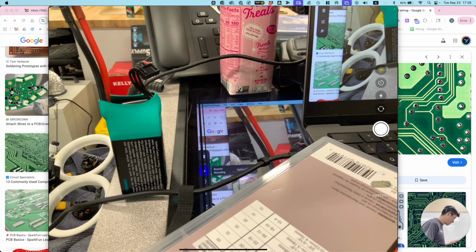Go ahead and place that split behind, and then slip the heat shrink on top. There you go. And then keep putting the heat shrink until it covers, and then if we touch down, we don't want any of that plastic split showing, so tuck it in. It doesn't show on the other side, right? Barely. Okay, and then is the solder joint in the middle? I feel it. Yeah. Perfect. Go ahead and heat gun it.